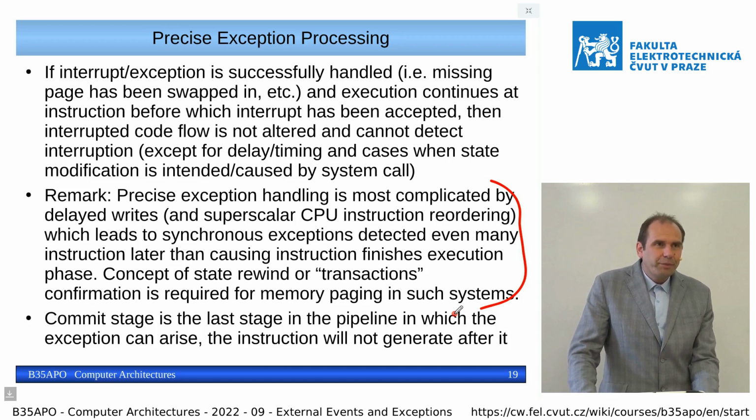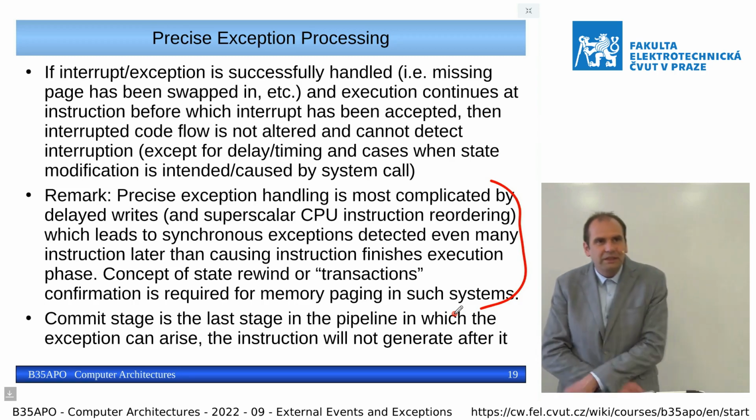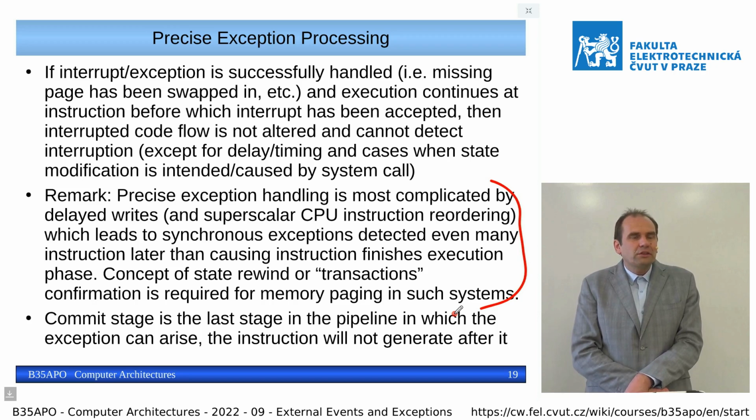So when the processor was equipped with an external memory management unit, and that signaled that you cannot access the memory because the page is not present, then the processor was not able to resolve the situation.